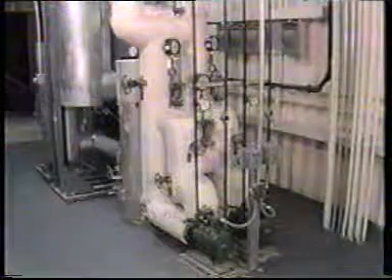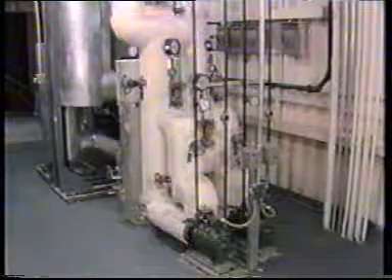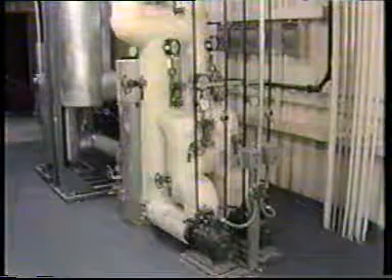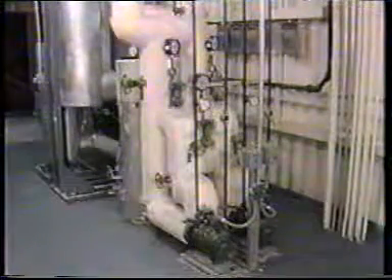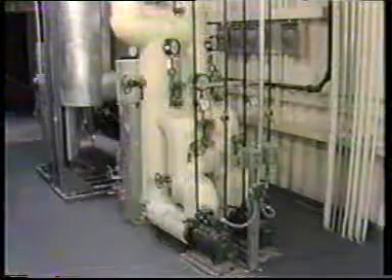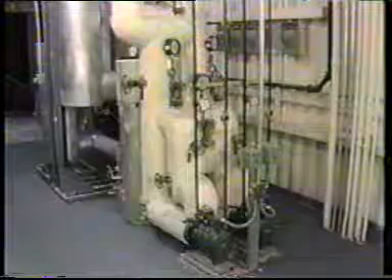Usually, the effect of pressure on the density of solids and liquids is so small that it can generally be ignored. However, its effect on the density of gas is very pronounced, and it is a factor that must be considered when designing systems to measure the flow of gases.